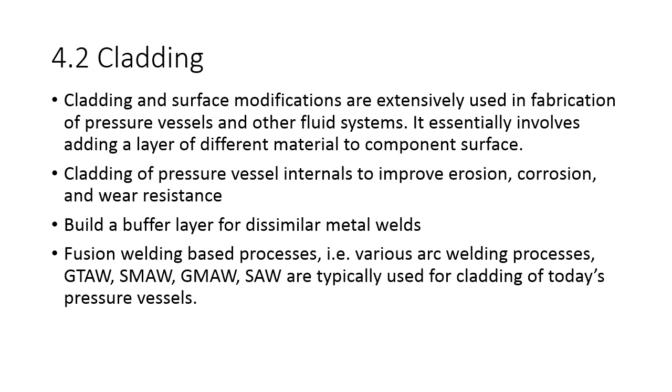Carbon steel's cheap. It's pretty strong. It's easy to work with. So we'll do what's called cladding. So you put a thin layer, or a specific thickness of a layer, of a material that's got good erosion or corrosion resistance on the inside of a pipe or a valve or a pressure vessel or a heat exchanger or whatever. You've got the outer material, which is the strength generally, and then the inside, the cladding, is the corrosion resistance.